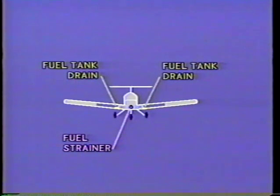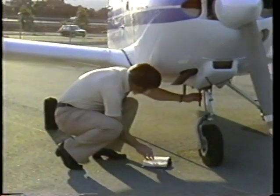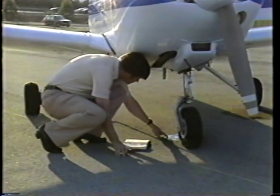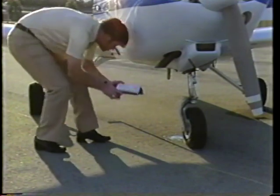This is the low point in the system, and the aircraft will have a drain on this point. During the pre-flight you can drain the fuel from there, and if there's any water that condenses in the system, it can be drained out at this low point, since it will settle there as water is heavier than fuel. And from there it goes up to the engine-driven pump and on to the carburetor.